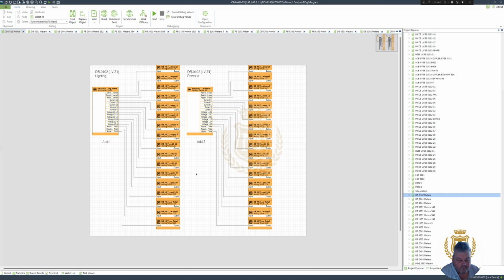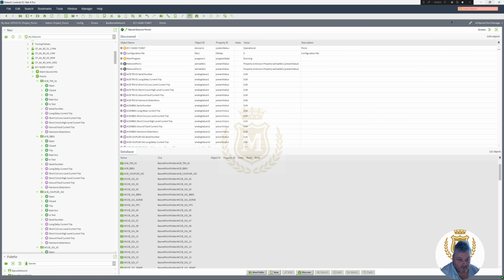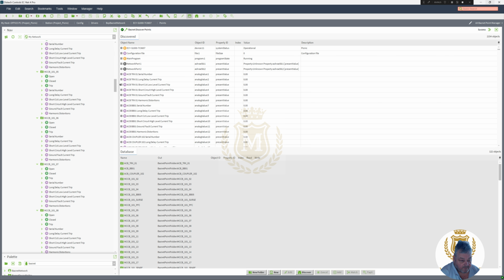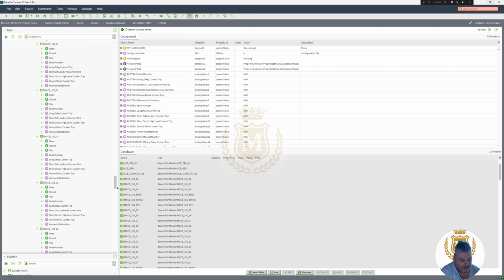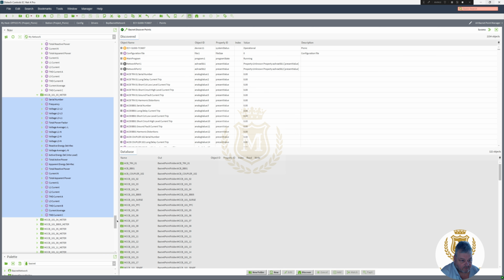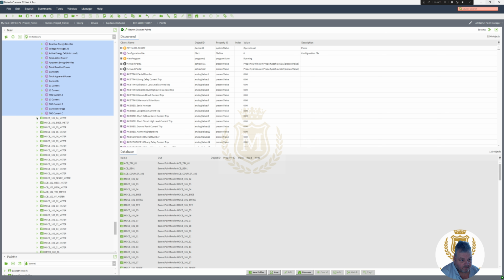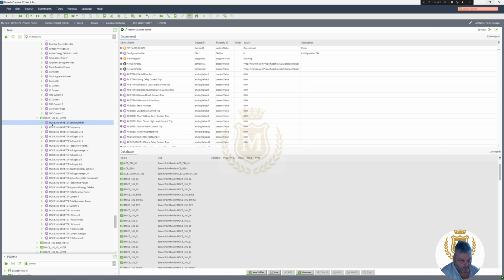Where if we had used a Modbus RTU to Modbus IP and brought them directly into Supervisor, then we would cut out all this tedious work that we're doing here: taking the point in, making the folder, putting the point in the folder, and then stripping out the words for the meter.